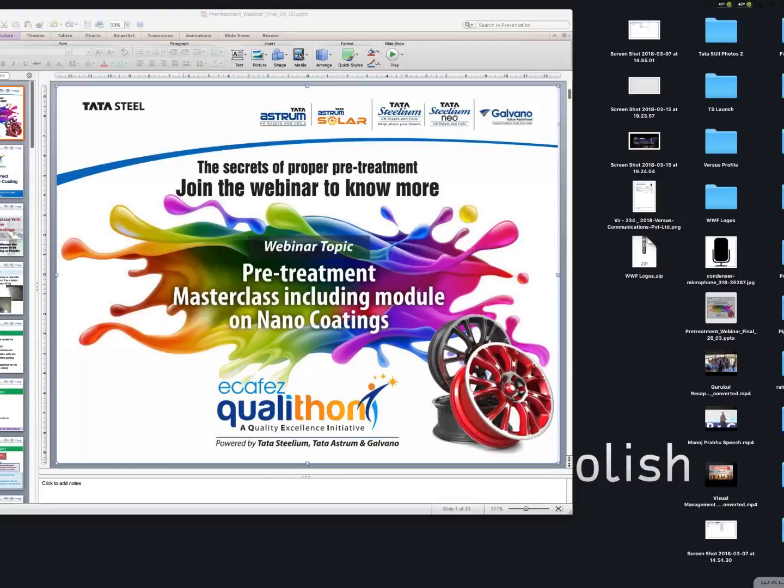If you have a simple job where oil presence is less and you are not into EDD, that is extra deep draw or deep draw pressings, and you are not adding any oil in the earlier stages, one tank degreasing should be good enough for you. Don't add anything, no need. If you are really confident that your degreasing is happening correctly, don't do anything.